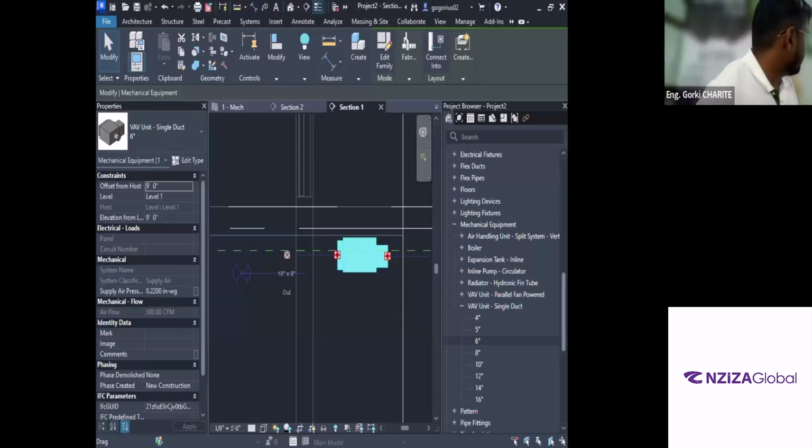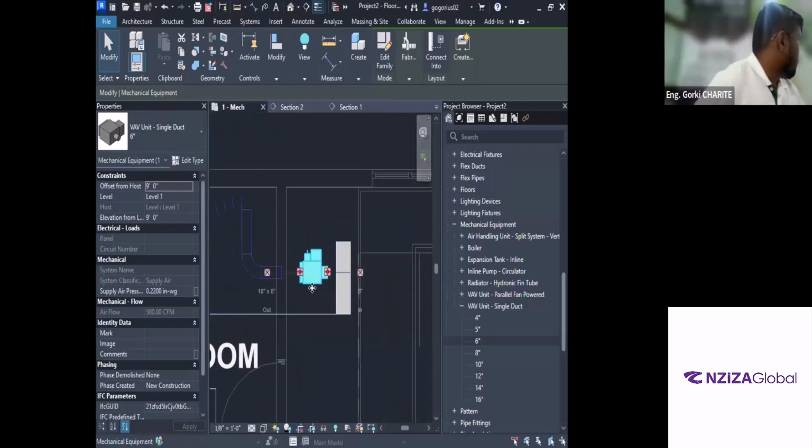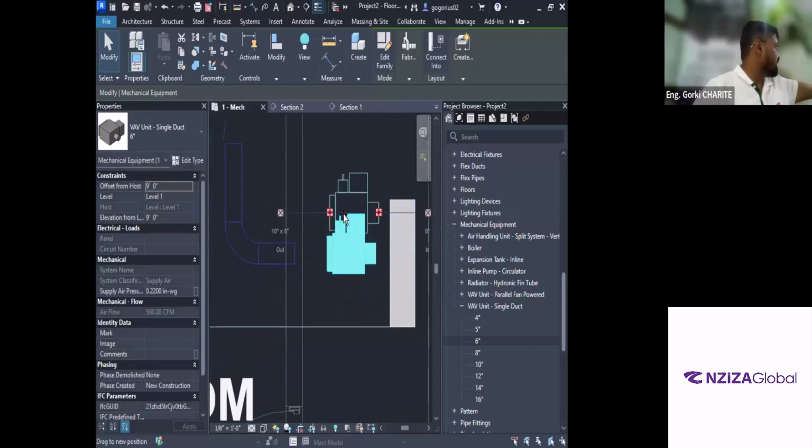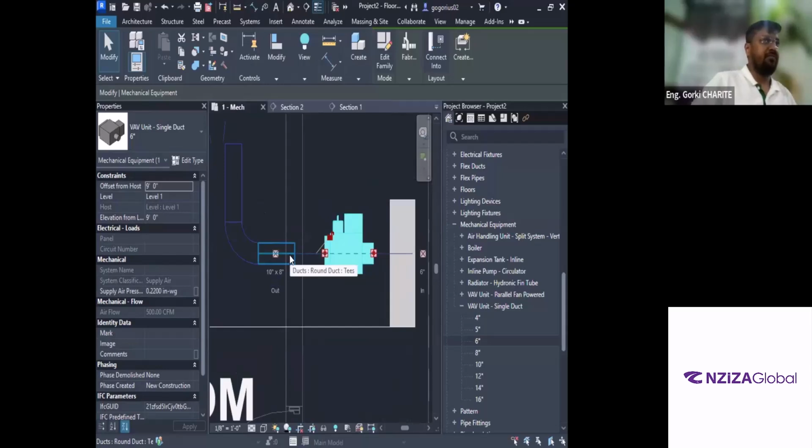All right, so I'll share my screen again. For the folks online, I was mentioning when we come into the floor plan, if you try to move stuff around in Revit, it will try to auto align itself. Right now, this VAV box center line in the horizontal axis is aligned with the center line of the duct. But as I was saying, two views, one plan view and one section view turned on for coordination will be very beneficial. All right. The reason we'll take a look over here, we'll go to this section view, and now over here you see this is our VAV box and this is the duct that we were talking about.